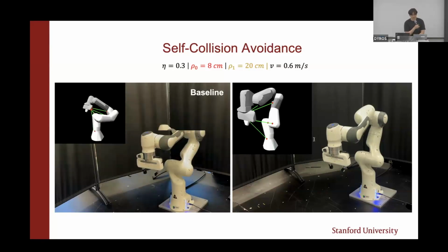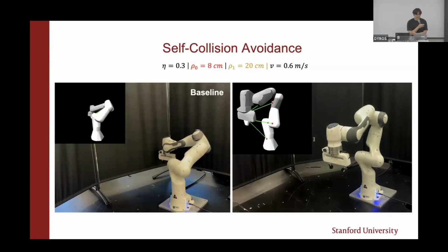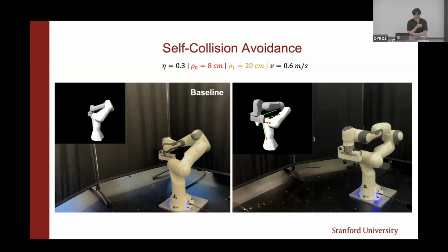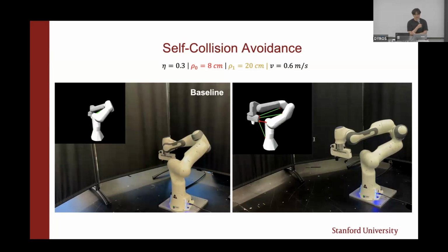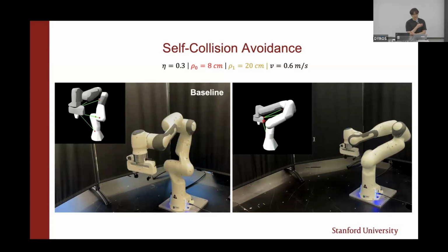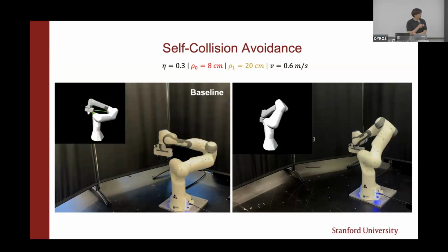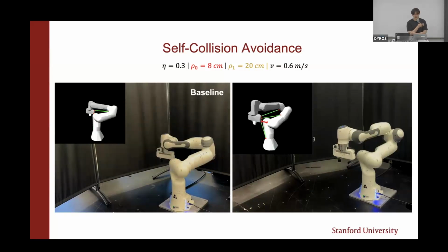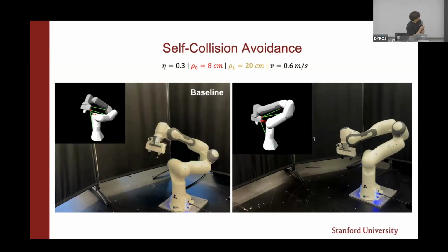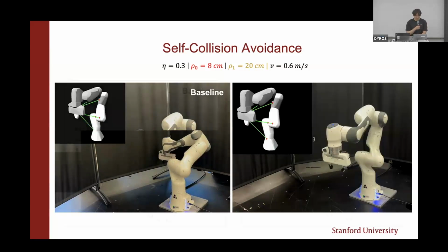In the second video, the same experiment is performed using the approach where the end effector reduces its velocity approaching self-collision and smoothly traverses around its lower links. Eventually the robot exits the constraint task and restores its normal operational velocity. To note, this is a very fast approach velocity, about 6 centimeters per second here. It's unfortunate that you can't see the video, but it's quite dramatic bouncing.